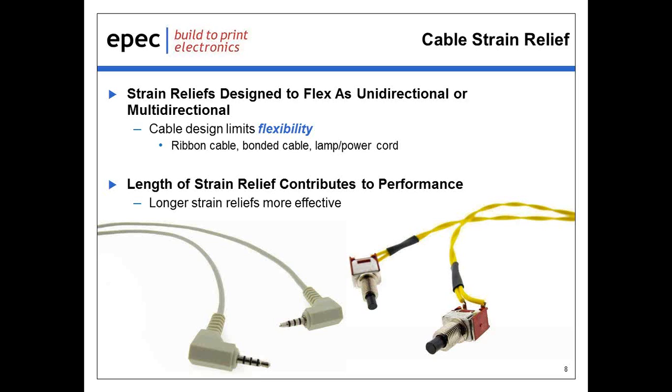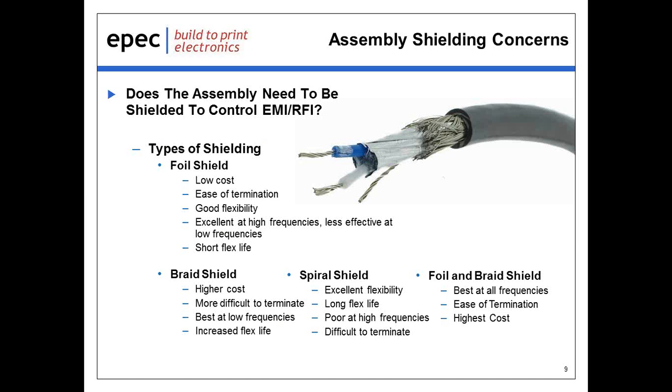The length of the strain relief does affect how much of the load of any movement in the cable is transferred to the termination point. The longer the strain relief, the more effective it will be in protecting the termination points. And again, we understand we may not always have a lot of room to make a longer strain relief, but the longer the strain relief, the more protection you'll get.